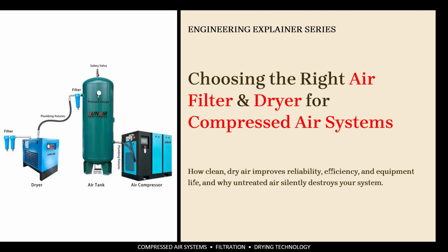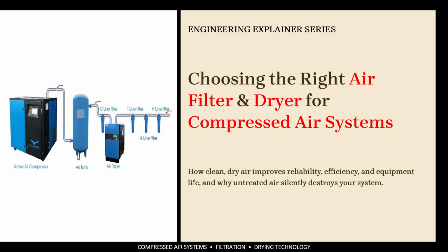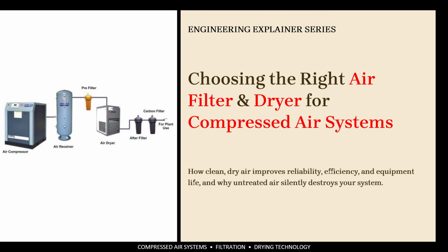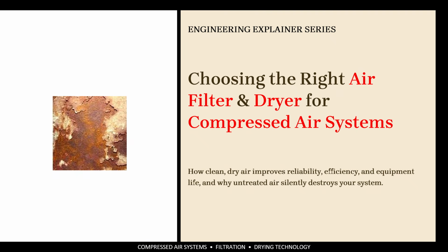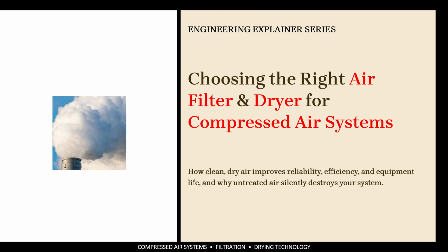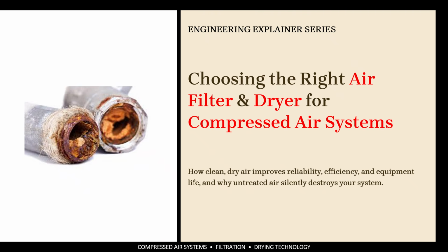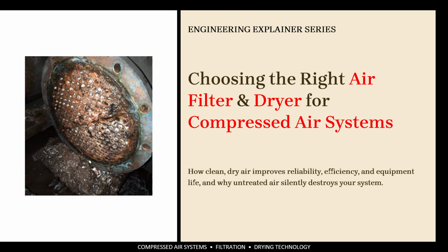Welcome to this engineering overview on selecting the right air filters and dryers for compressed air systems. Compressed air may look clean, but in reality, it often contains moisture, oil aerosols, dust, rust particles, and other contaminants. Without proper air treatment, these contaminants can damage equipment, increase maintenance costs, reduce system efficiency, and even affect product quality.